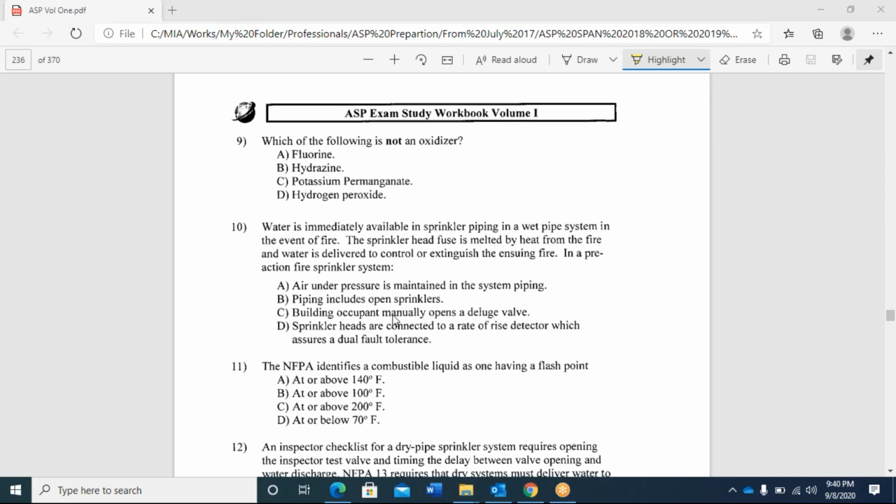When it comes to the freezing state, then in that environment we need a dry pipe system, because if there is water inside the pipe and it freezes, and if any fire occurs, the pump will not give you the pressure, because your pipe system is already jammed. So generally we are using this type of system in cold environments, just like Canada, some states of America. We can say, let's suppose if you want to install in the northern area of Pakistan or India, in that area we need the dry pipe system.